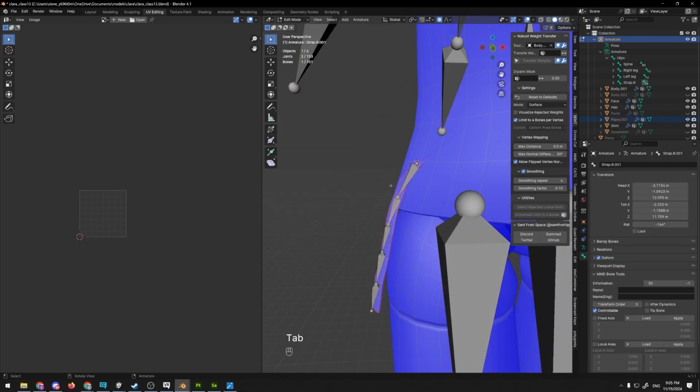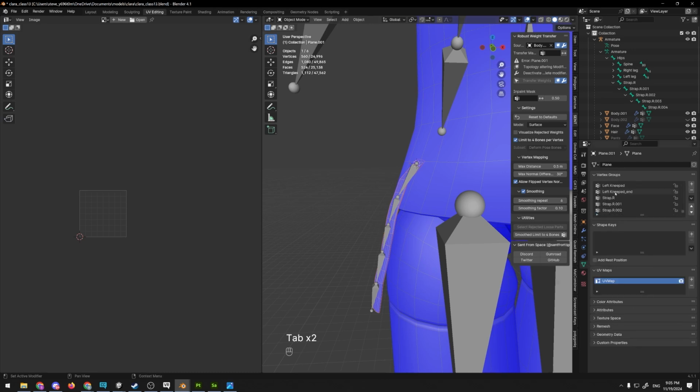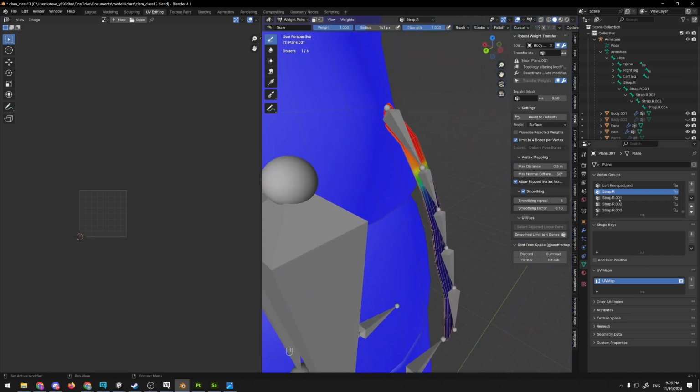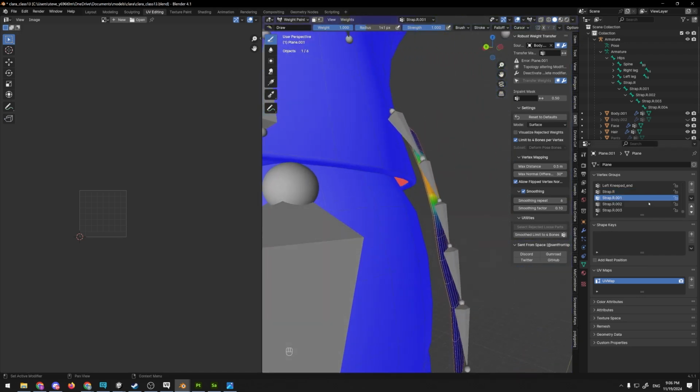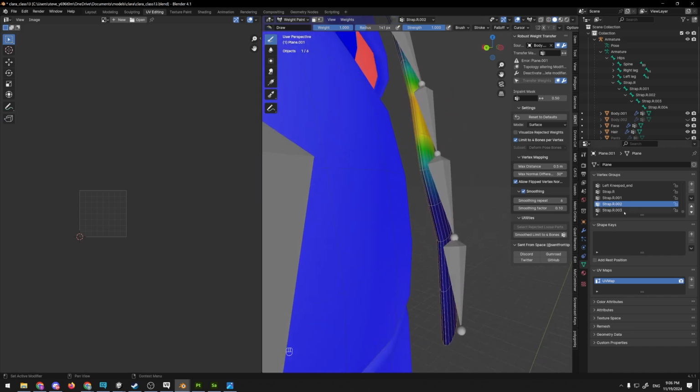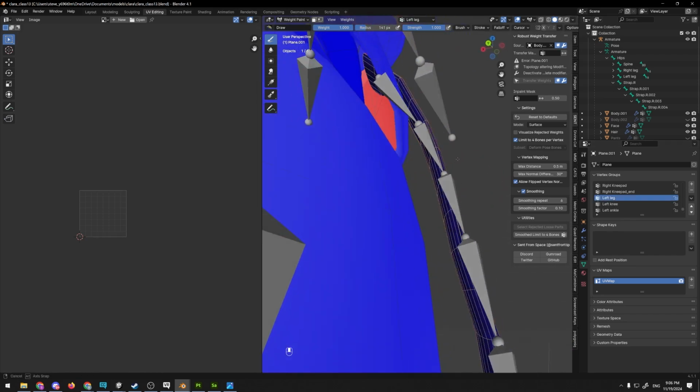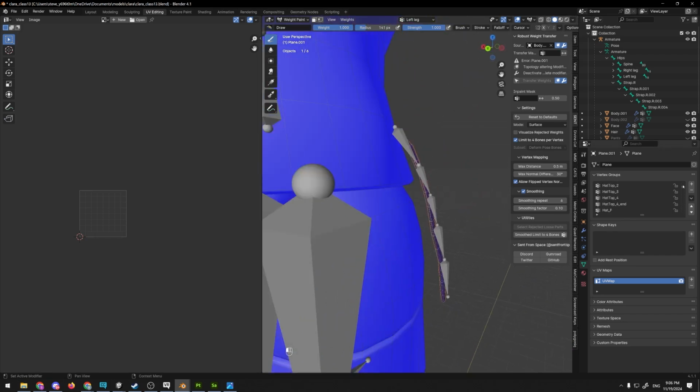And if we do that and did it right, in theory, we'll see our vertex groups over here. Way more than we need, but I bet you it actually did it right if we go to our weight painting tab. And see, strap R is the top of the strap. 001 is down a little bit. 002 is down a little bit, matching the bones perfectly. Some of these other, like the left leg, might have gotten a little bit of painting in here. Looks like it didn't. We got lucky. To fix this, you can either just go remove these vertex groups that don't affect it. So I know that the head, for example, is not going to affect this strap.